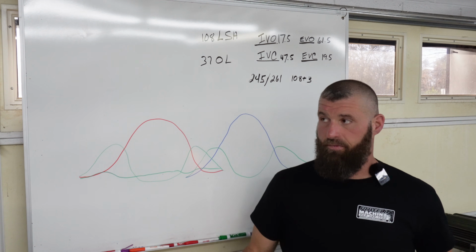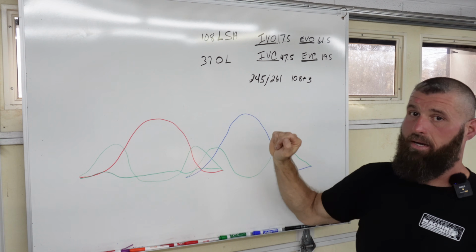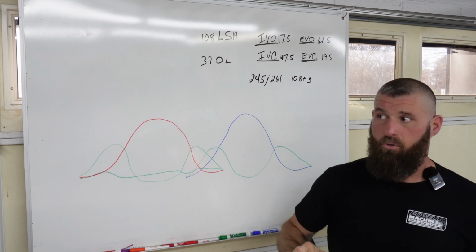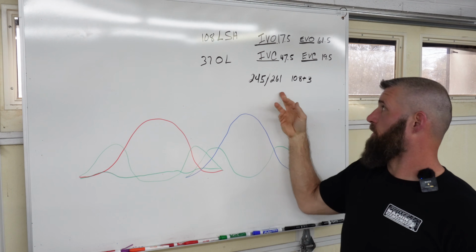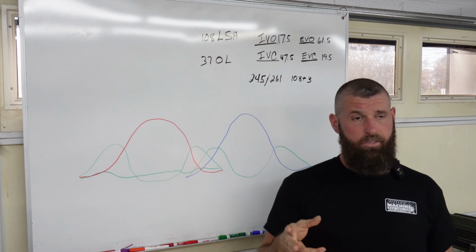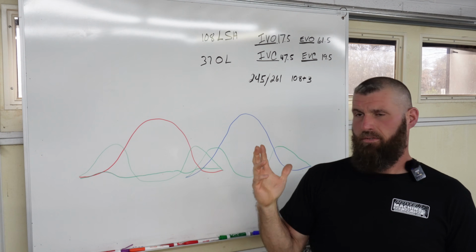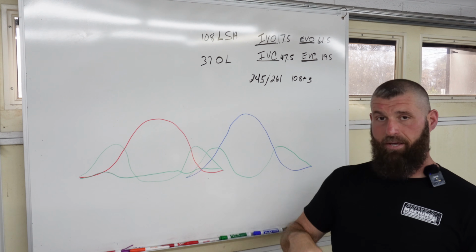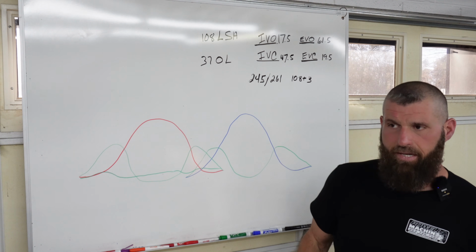And these are the specs for that camshaft. And all of this is at 50. And we're going to talk about why that's important. But this cam is 245, 261, 108 plus 3. And I think it was a 400 lobe on the intake and 395 lobe on the exhaust, and that comes up to, I should have done that math, 640 on the intake and 630 or 35 on the exhaust or something.